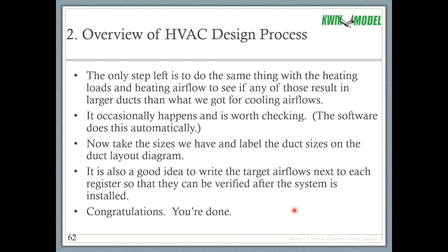Now, as I mentioned earlier, we started off sizing everything to the cooling airflow, but once you do the same thing for the heating airflows, you have to look at each room and compare the heating airflow to that room to the cooling airflow of that room, and pick the higher of the two. You want to size your ducts to the higher of the two. It occasionally happens that the heating airflow number will be higher, so it is worth checking. The good news is that the software does that automatically. You don't even know about it, and I will point that out when we do our example.